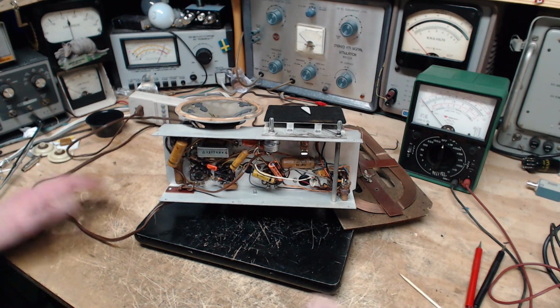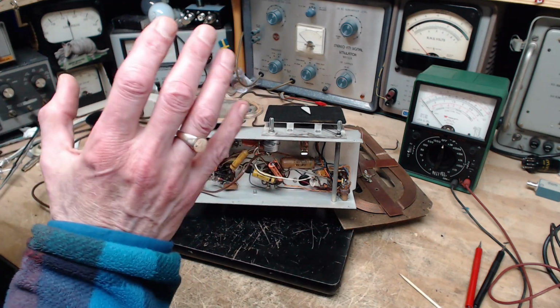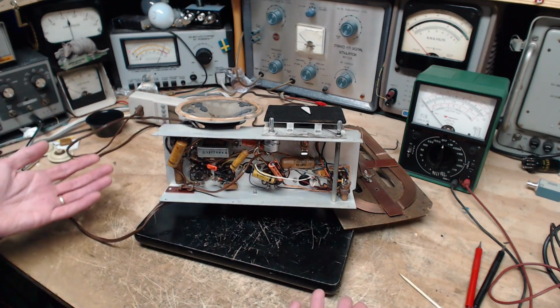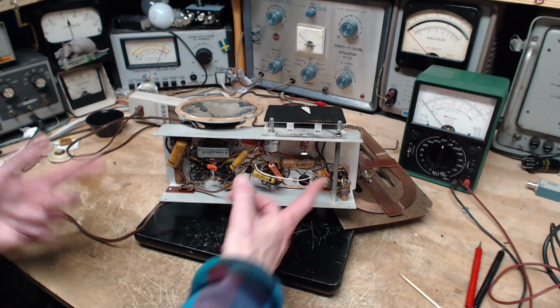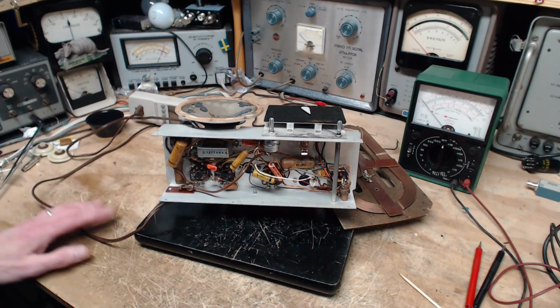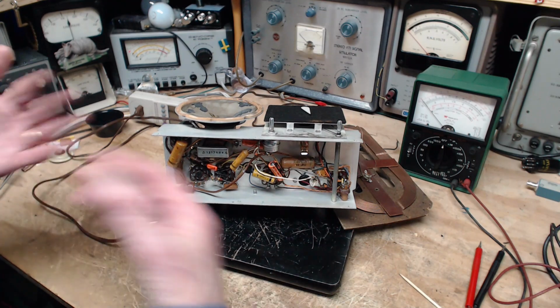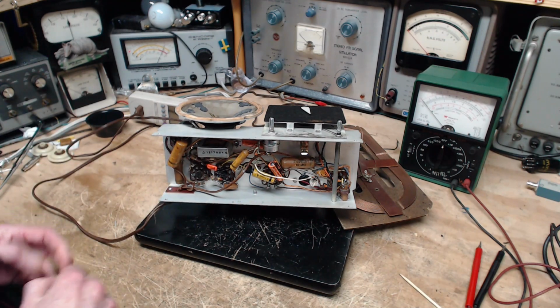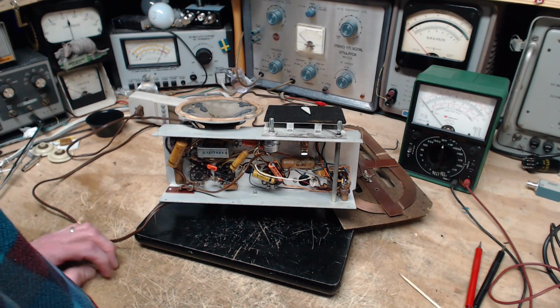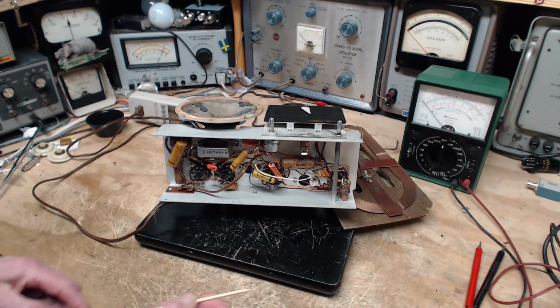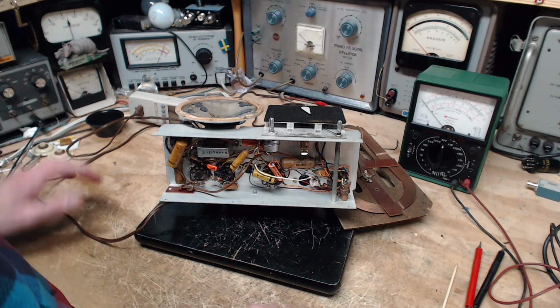So what I want to do is a before and after test. I want to test the radio in its current state with this capacitor in place, get some idea of what kind of current leaks through it onto the chassis that might shock me or somebody else, and then change the capacitor with a new one, and then repeat the test and see what happens. Now, I just did this with a tube and ended up discovering something quite obscure. So I'm always open to learning new things, and I'm also very open to having my paradigmic thoughts corrected. Paradigmic, is that a word?